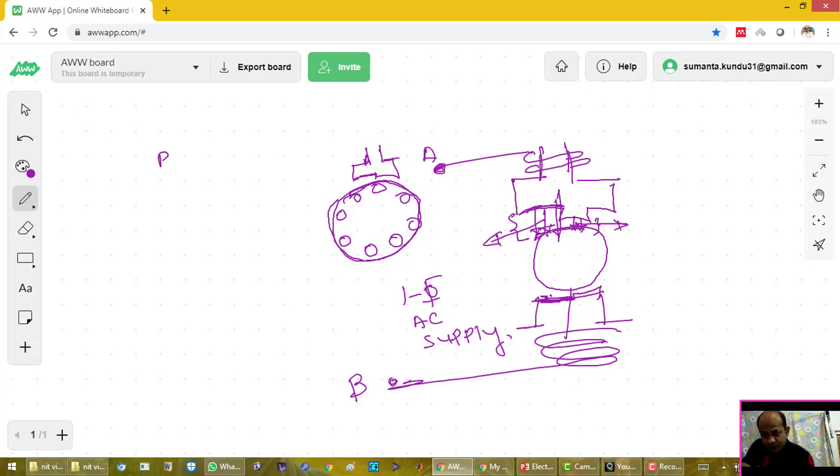As a result, reluctance is varying, because reluctance depends on the length of the air gap, and here there are two different air gap lengths. So the flux path varies from stator pole to rotor. Now my question is, what will happen due to this variation of reluctance?